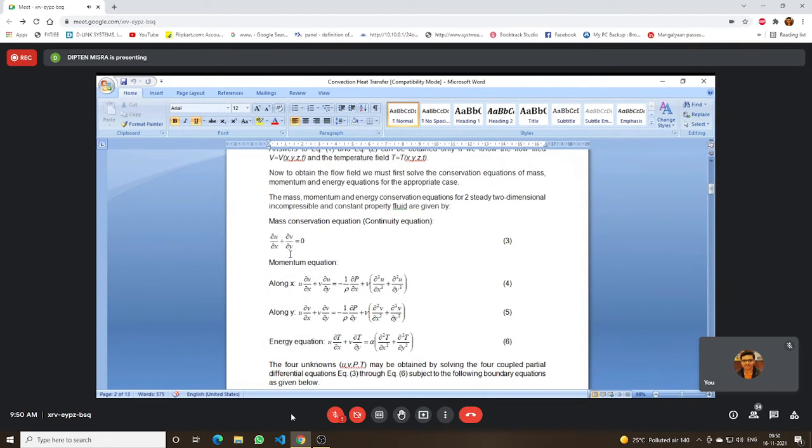And x and y, they are what? The independent variables. And the dependent variables are the velocity components u and v. Now, so what we do is that only the mass conservation equation is not sufficient. We take also help of the momentum conservation equation along x and y. So we require to introduce the momentum conservation equation. One is momentum along x given by this form of the equation. I think you have already studied this equation, it is known as one component of the Navier-Stokes equation. Yes, sir, you have come across this thing.